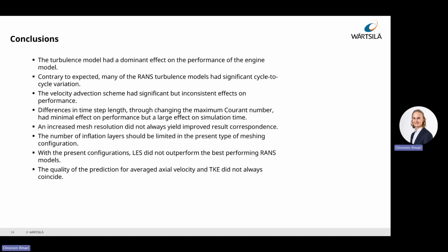Differences in time step length through changing the maximum Courant number had minimal effect on performance, but a large effect on simulation time. An increased mesh resolution did not always yield improved result correspondence. The number of inflation layers should be limited in the present type of meshing configuration. With the present configurations, LES did not outperform the best performing RANS models, and the quality of the prediction for average axial velocity and turbulent kinetic energy did not always coincide.